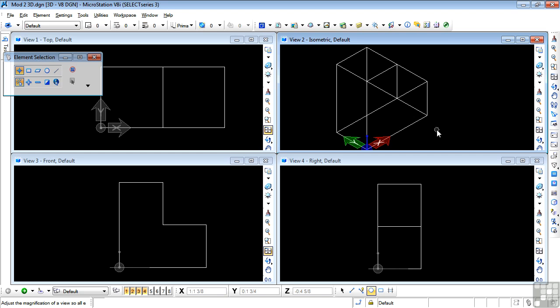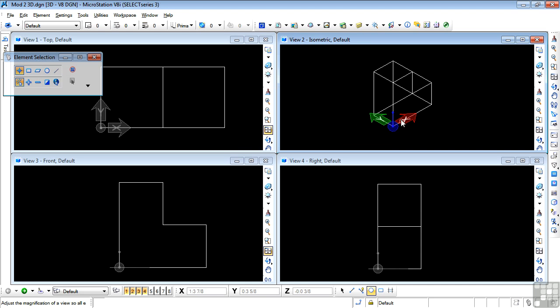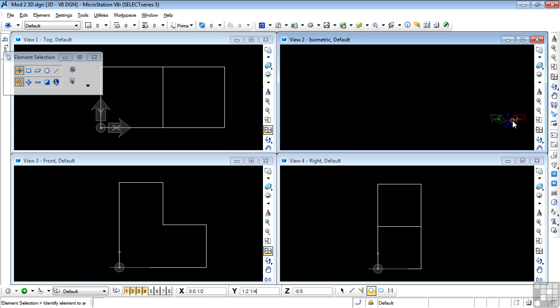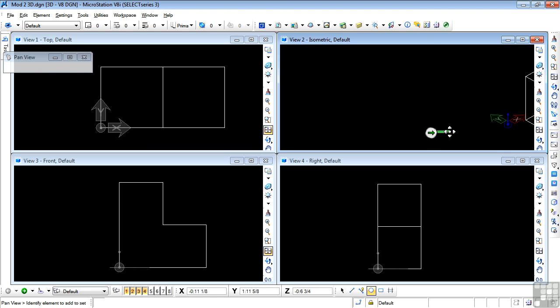And one last thing you can try. Right now we have the ACS icon neatly at 0,0 and our elements starting at that point. But what happens if I zoom this drawing? Watch the ACS carefully. Note that as I zoom the elements off the screen, the ACS icon does not leave the screen. So really, it's abandoned its location, if you wish, at 0,0. Technically, it's still there, but it's not displaying there. So this can be a little bit confusing at first.